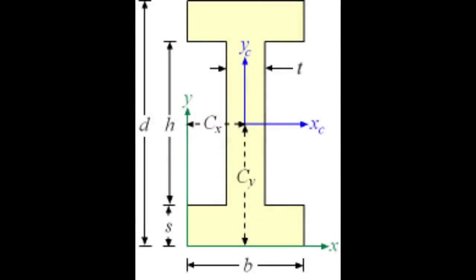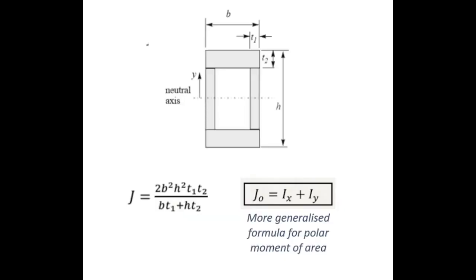We contemplated many designs and discovered through research that I-beams, though massively effective against bending, have little resistance to torsional loading, so would need to be modified. This is unlike hollow rectangular beams which, although generally have greater mass, have a higher polar moment of area for similar dimensions. Eventually we began testing on the most promising designs.